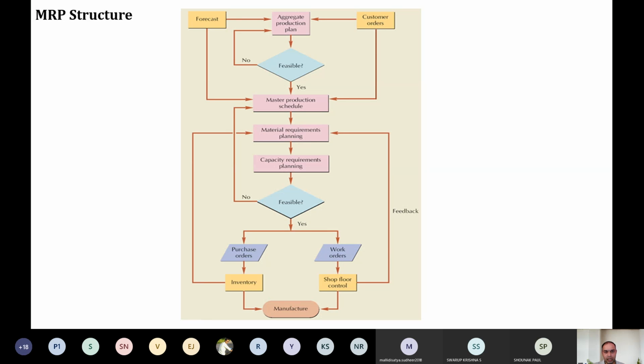To manufacture these 22 cars, they will prepare the material requirement planning. Say for example, on coming Monday, you plan to produce 22 cars. So I will consult with my supplier, and my supplier will tell me what parts are available. I will contact n number of suppliers depending upon the number of parts required, I will discuss with them, and based upon their commitment, I will release the purchase order if I'm going to procure the items.